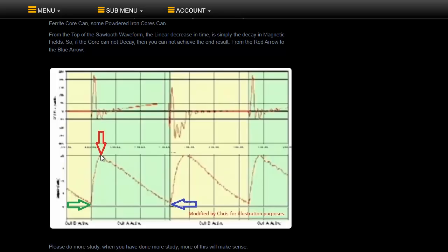It's because of the reduced impedance effect. What's happening here is the two output coils have such a low impedance that their magnetic fields can ramp up very, very fast. They can get to peak value very fast.